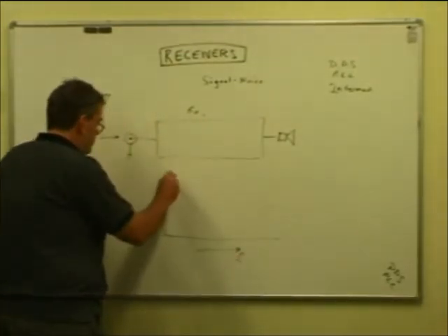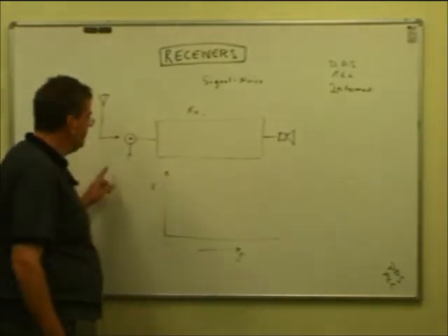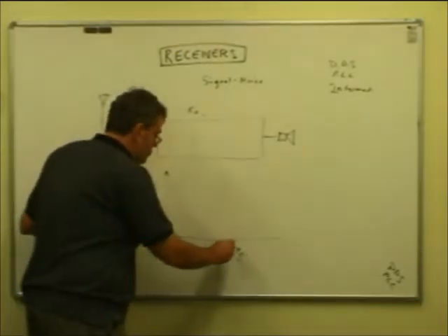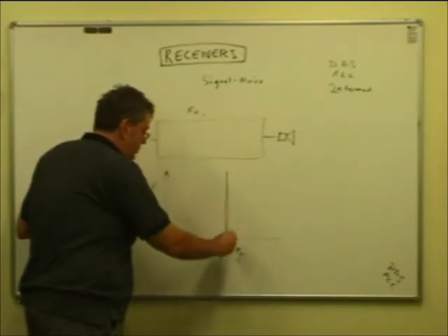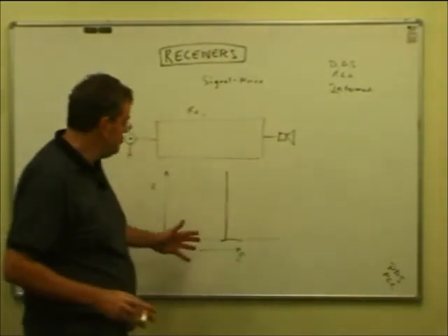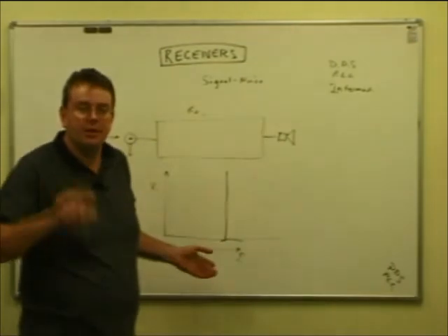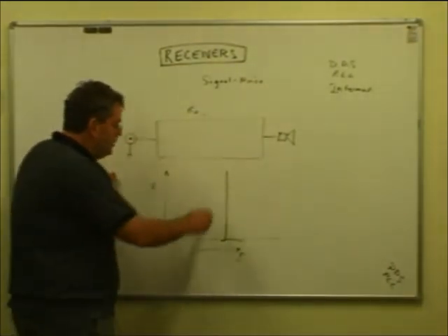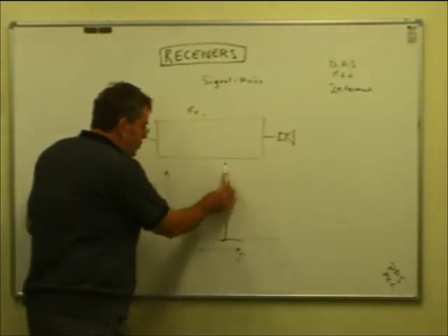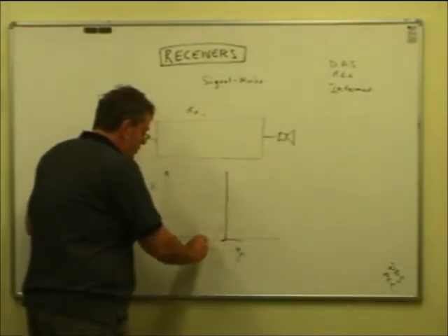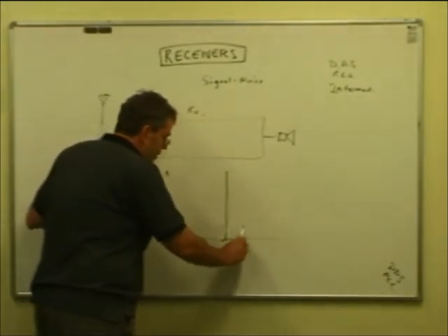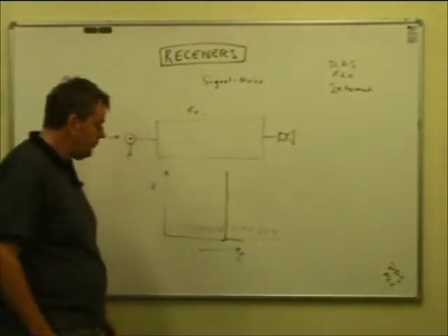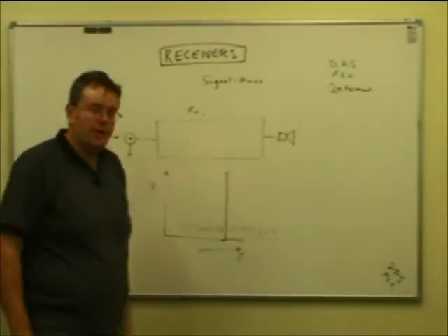That's the strength of the signal, or the voltage of the signal arriving. And if it's a very, very strong signal, we'll just draw it as one line, a single sideband. Let's say it's a Morse code signal when the key's down, so it'll just be continuous carrier. Now, coming in through the terminal, there'll be the signal we want, but there'll be noise. And you can draw it as sort of this random stuff, distributed up and down in frequency, all the way down to very low, way up to very high frequencies.